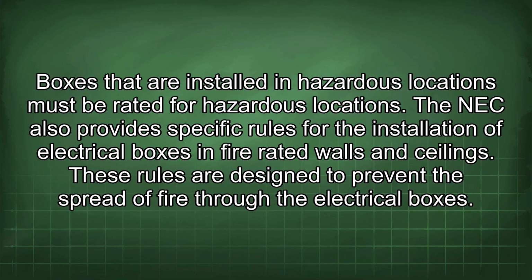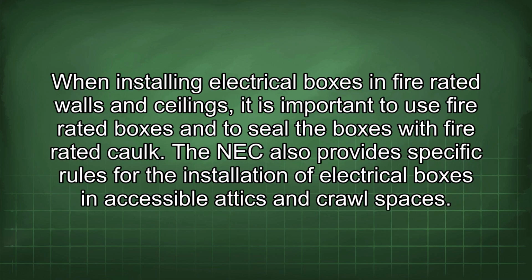The NEC also provides specific rules for the installation of electrical boxes in fire-rated walls and ceilings. These rules are designed to prevent the spread of fire through the electrical boxes. When installing electrical boxes in fire-rated walls and ceilings, it is important to use fire-rated boxes and to seal the boxes with fire-rated caulk.